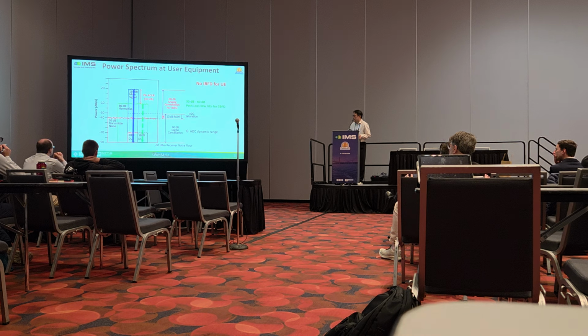For the user equipment case, we can also consider this as a small cell RU, radio unit, case. So our output power is only 20 dBm, and the noise floor is going to be the same. So the required cancellation is relaxed. And another thing, for the sub-band full duplex case, the interference, which is due to the PA etc., comes from another, different UE. So not that much isolation between the UEs is required.